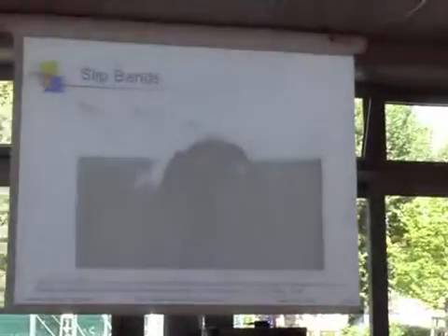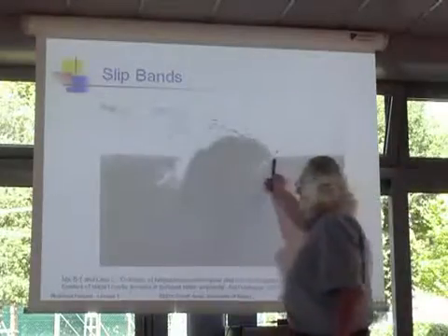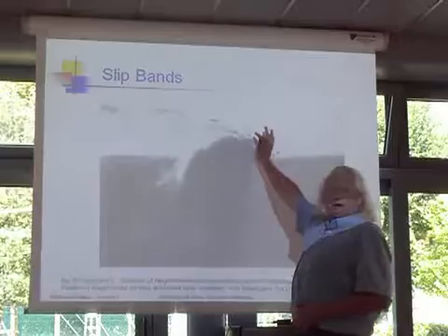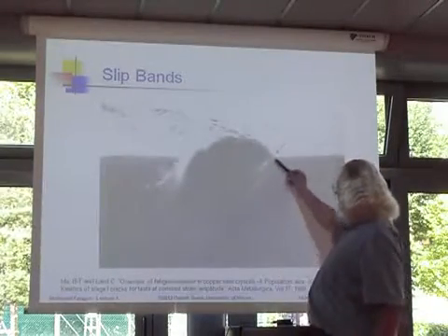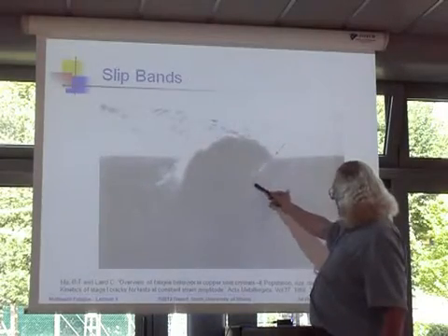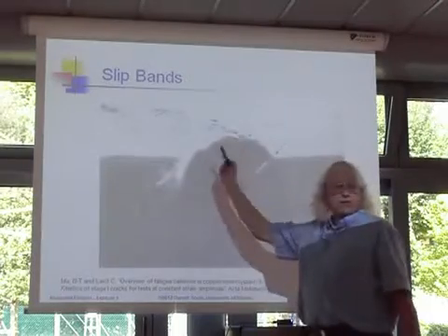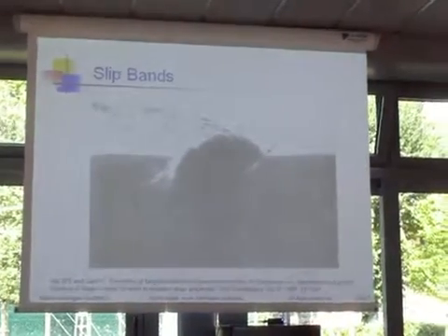And you can see that these slip bands are real. Here's one that's actually in section. So this, of course, started off completely flat across the top, and you can see how this material has come out of the surface. And you can also see how a crack is formed. So there's one. It jobs over and comes down. One is forming there, and you can see one forming right here, and so on. So sooner or later, everything will form a crack. If we cycle it enough times, sooner or later we'll always get cracks.